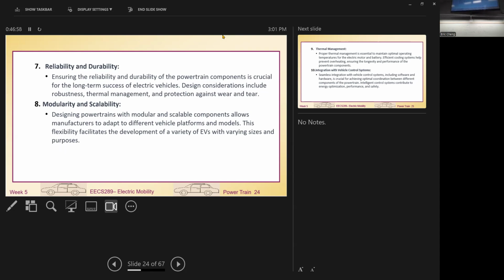Like the motor we try to use, we tend not to use a plain DC motor, we tend not to use an industrial motor, we tend to use a special DC motor. And to increase reliability, some are multi-phase motors, where each phase can be independently controlled. Or we tend to use an SR motor. So each phase has independent control, and then we can have higher reliability for the motor.